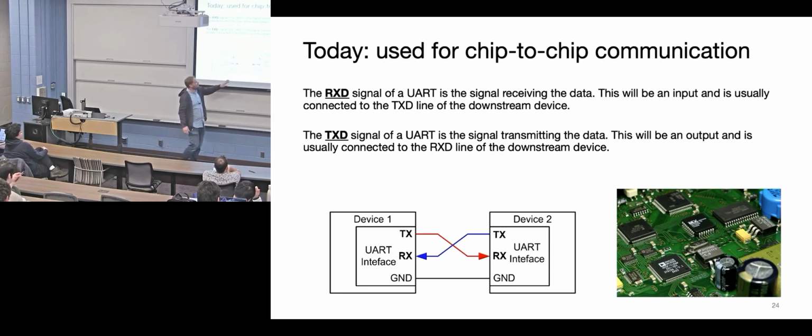The nice thing about this one is there's no need for a clock. Does anybody remember how you actually figure out the timing then? How do you figure out timing and phase? Yes. It pulls down the line for a certain amount of time and oversamples to figure out how long it was held down, and then uses half of that length to sample.